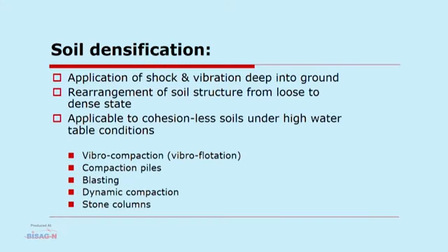Soil densification is the application of shock or vibration deep into the ground, causing rearrangement of soil structure from a loose to a dense state. It is applicable to cohesionless soil under high water table conditions, which can be done by vibro compaction, vibro flotation, compaction piles, blasting, dynamic compaction, and stone columns. All these five techniques, which come under soil densification, we will be discussing in this video.